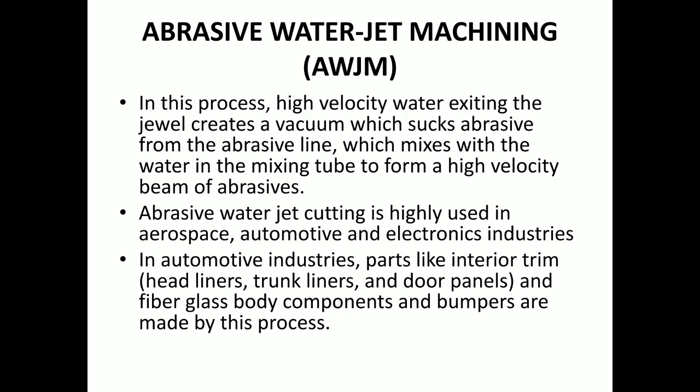Now coming to the next slide, abrasive water jet, in continuation to the previous slide. What is this process all about? In this process, high velocity water exiting the jewel, that is the nozzle, creates a vacuum. The jewel is a mixing chamber, which sucks the abrasives. Water is coming into the jewel with high velocity.